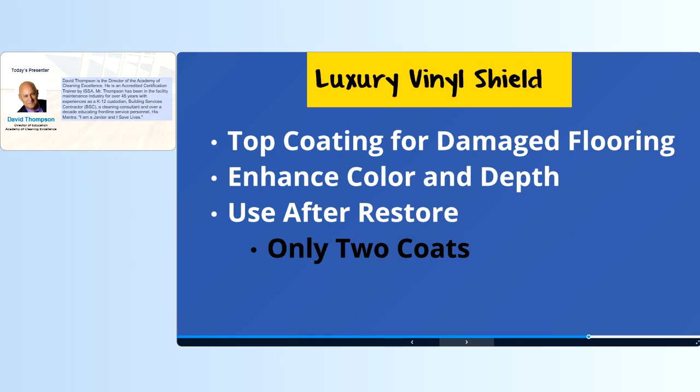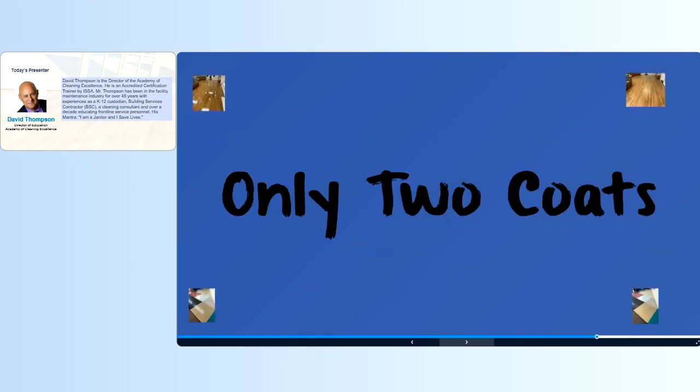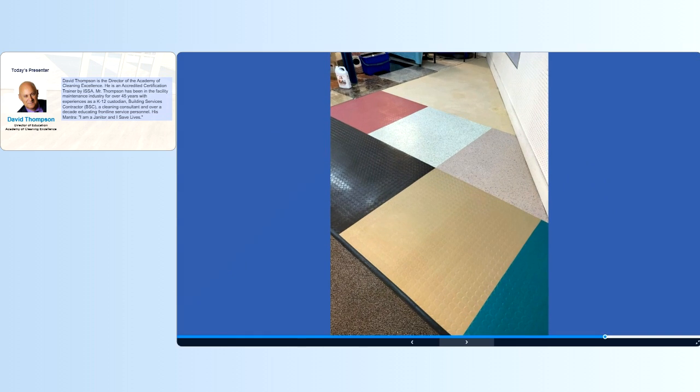Now, one of the things, remember, this is a non-porous floor. It does not require 4, 5, 6, 10 coats. Only 2 coats. Basically, just so that you get even coverage, folks. That is it. Do not apply multiple coats to these floors. Only 2 coats. Now, with most of these products that are out there on the market today, we can also use these on other synthetic floors as well.